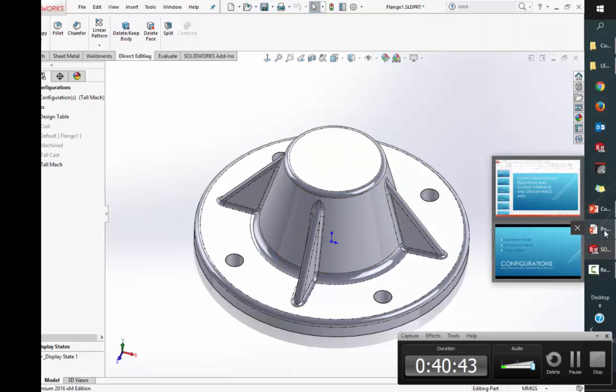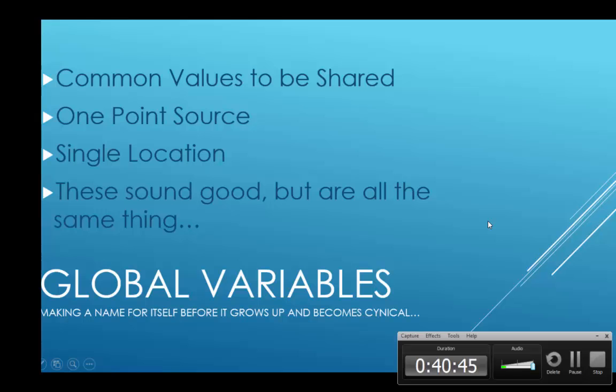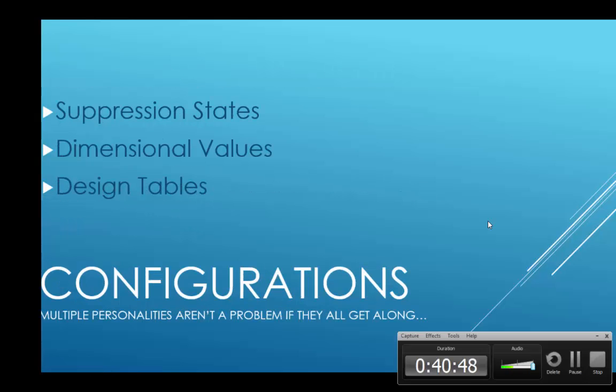You create the table in Excel first. Does it still store it in the file, or where does it get stored? Well, if you create it outside, which is highly unlikely and a big headache, which you can do, what I have done in the past is I've protected my files that way. So what I'll do is I'll create a design table in SolidWorks, I'll copy it, put it into an Excel file, put that Excel file in a network location that only I have access to change, and then I go into my part and I hook it up to this external file at that time.